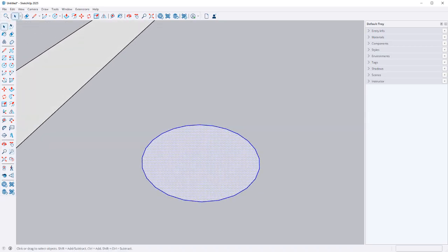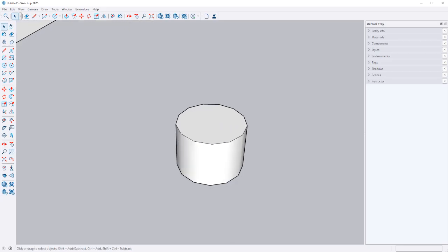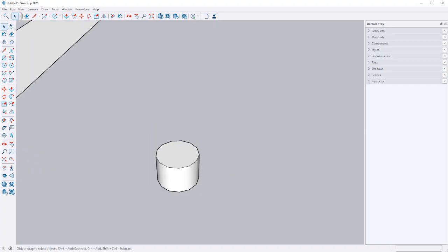So when you're working with some of these later on in the semester, if you start a circle, you might want to do something like 13 faces, and visually you might not even notice. Typically faces are rounded like this, but if this is something small in your model, you might not notice, so it doesn't hurt to reduce some of these sizes. You could even go as small as maybe, like 9.